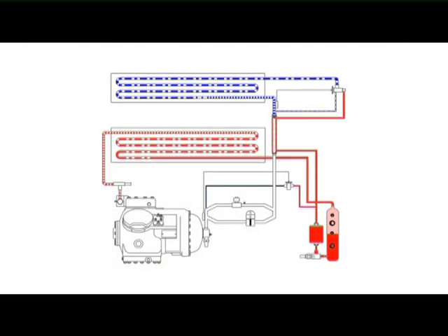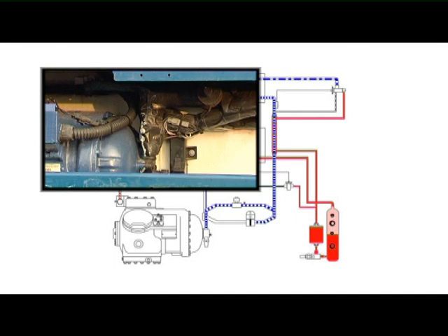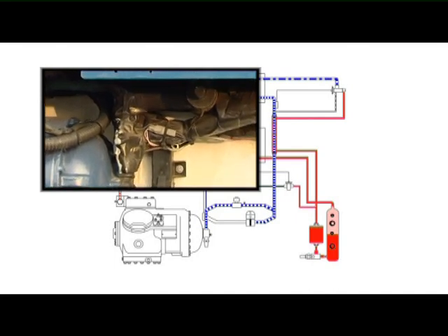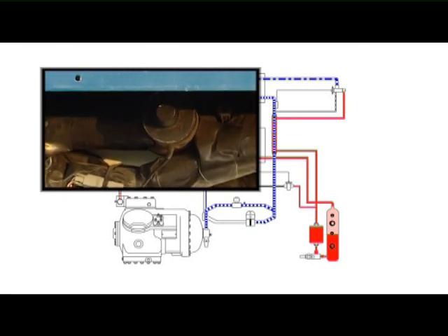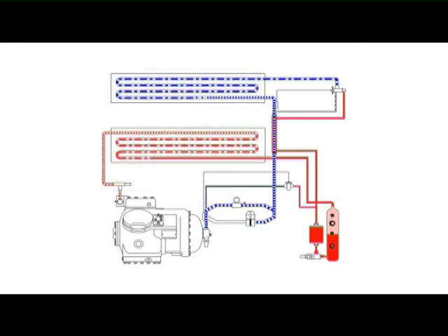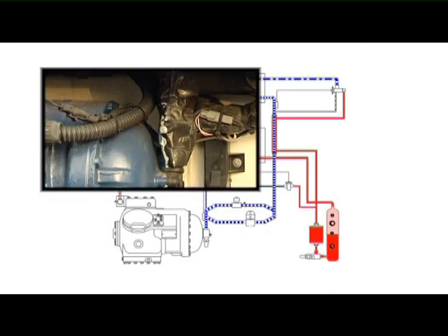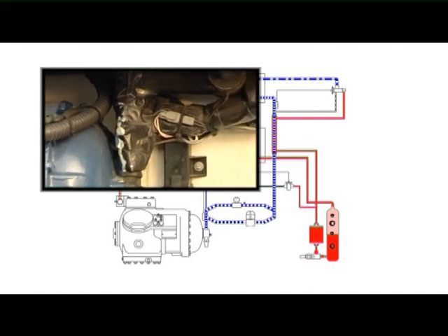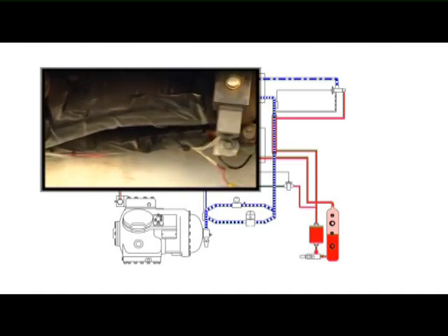The low pressure and the low temperature superheated vapor in the suction line passes through the heat exchanger and flows to the suction modulation valve. This valve is a valve with an infinity opening to ensure the system reaches the desired box temperature. For frozen cargo, when more capacity is required, the suction solenoid valve will open as well.